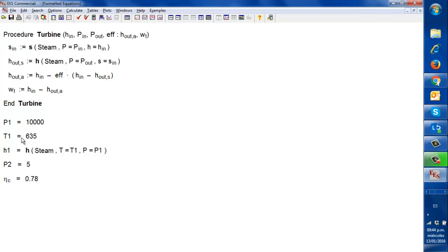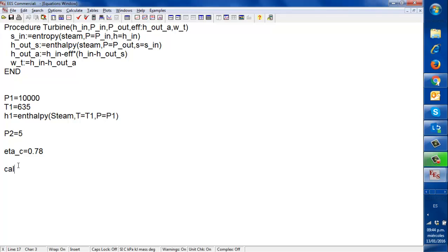So I can call it now. Call turbine. And what is my H in? H1, right? We have 5 minutes. What is my P in? P1. What is my P out? P2. And what is my efficiency? Eta C. Then colon. How do I want my H out to be named? H2A. And what is the work? I will set work.